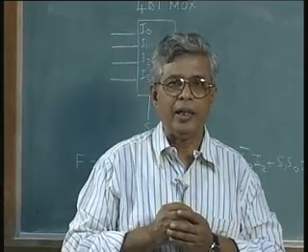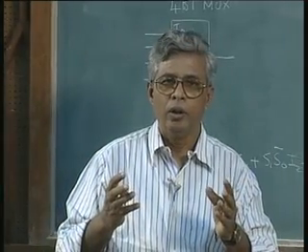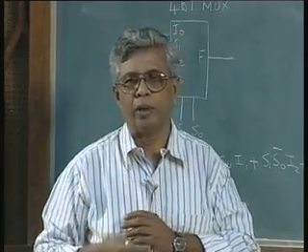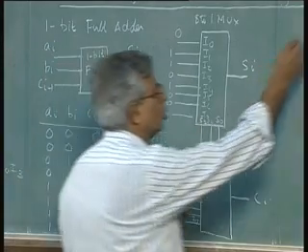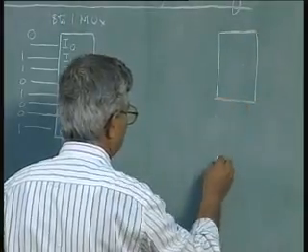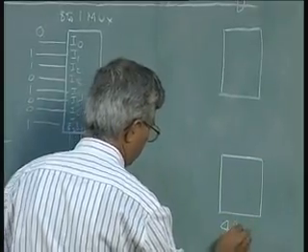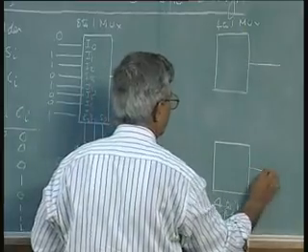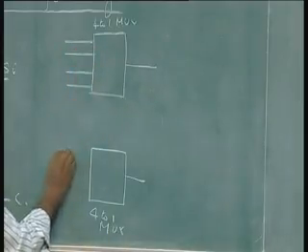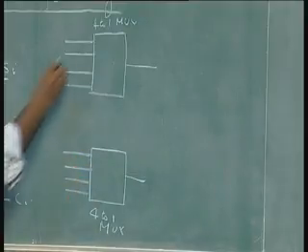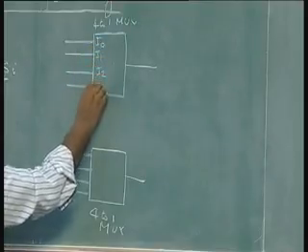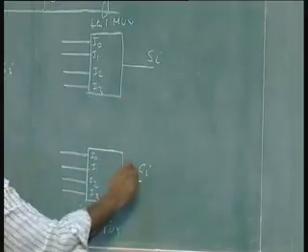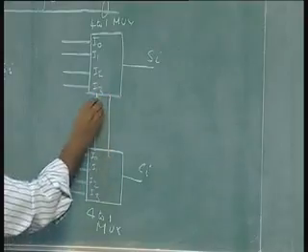Like in the Karnaugh map case, if you are given a free ride, you would use AND gates, OR gates, inverters. But if the person comes and says use only NAND gates, we will do some further manipulation. The same concept here, I am going to use 2 4 to 1 multiplexers. This is all I am allowed to use. I will get Si out of this, I will get Ci out of this, and there are only 2 selectors, S1 and S0.